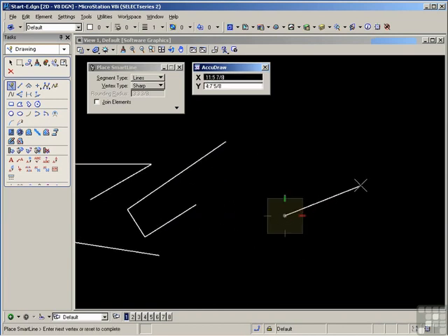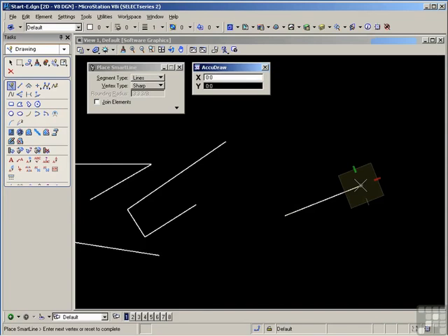What's happening here is that MicroStation is anticipating your next move. And it's assuming that you will likely want to draw at right angles to the previous line. So it aligns the compass with the previous line so you can quickly lock to one of the axes to place the next data point. If you are drawing in a rectangular fashion, you can place right angle corners very quickly. If your next line is not at right angles to the previous line, you can simply drag the line away from the axis to place a data point.